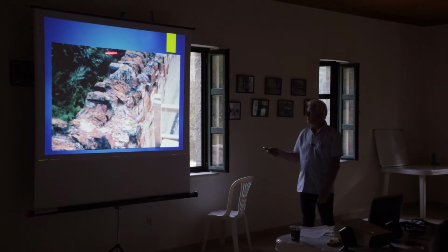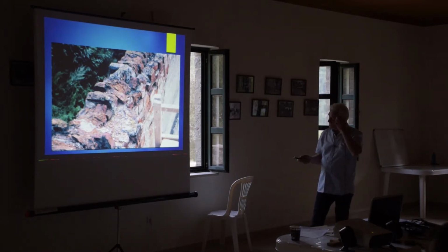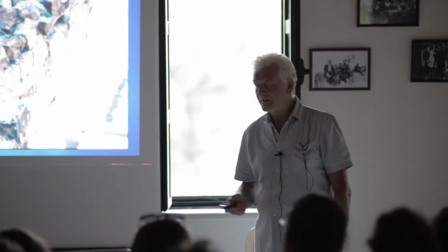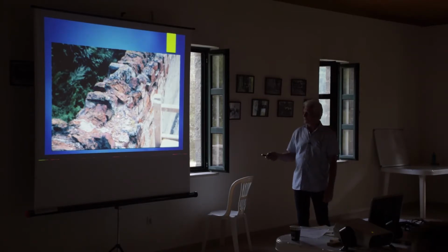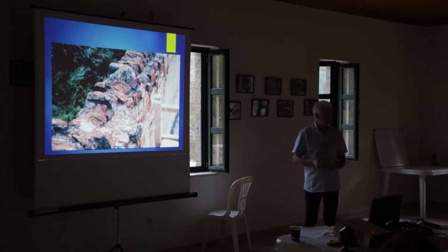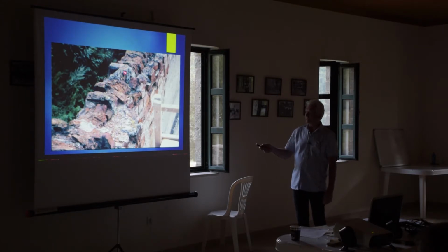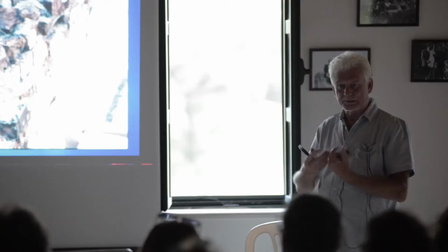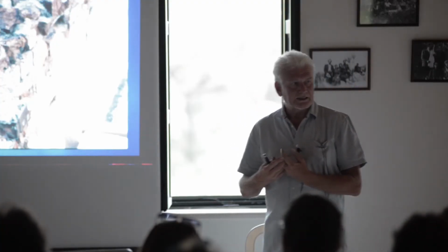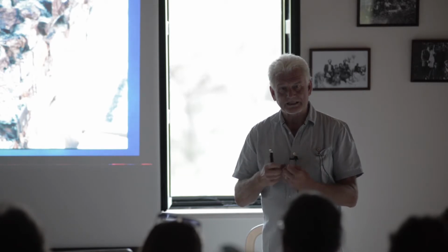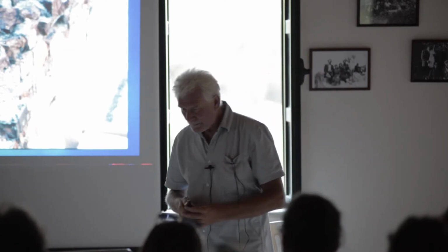Here, for example, this is a wall where the top part collapsed, but what it revealed was that the wall itself had cement mortar. And when the rain came, the rain couldn't get anywhere near the cement, so it found its way into the bricks. And when you get a winter, the bricks are softer, the bricks will retain the moisture, the frosts will expand the bricks and blow off the face of the brick.